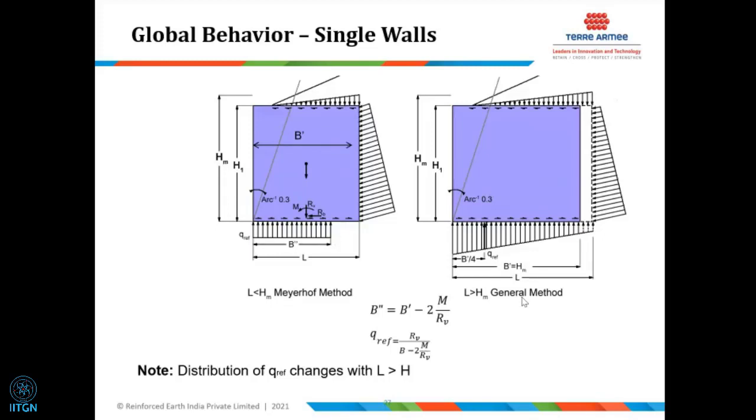And of course, it is not written anywhere, but this is general, and in some cases it is applicable, especially with a top slope surcharge, where the length of the reinforcement sometimes can be more. Also, in some cases of special foundation condition or global stability condition, you might have a situation, very rare, but still possible. That is when the trapezoidal distribution is used to calculate the stresses.